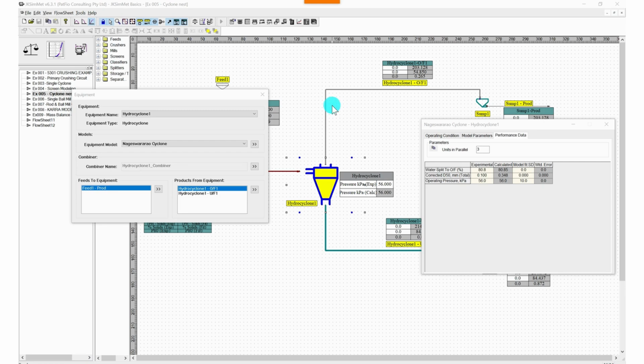The concentrator consistently fails to achieve nameplate throughput, and some plant operators believe that the SAG mill is undersized and capital expansion is being considered. For this type of problem, you can apply simulation technology, and JKSimMet to be specific, to have a full SAG mill circuit model developed in JKSimMet.